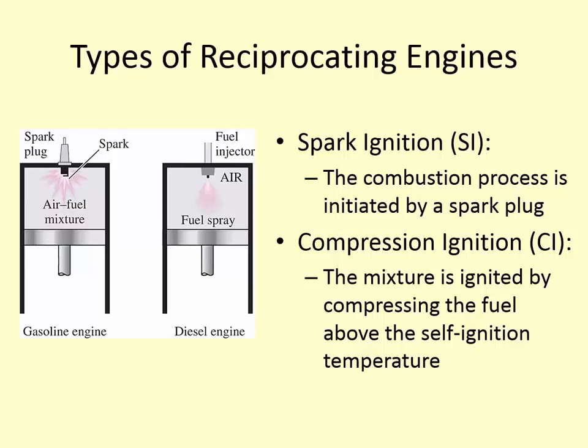On a very cold day, it's sometimes difficult to start a diesel engine, so they use a glow plug in order to heat things up a little bit first so that this fuel injection process can actually ignite. Because if your cylinders are all very cold, your block is cold, it's hard to self-ignite because an engine acts like a big heat sink, in that it's a large block of cold metal and it makes it difficult to ignite that fuel.